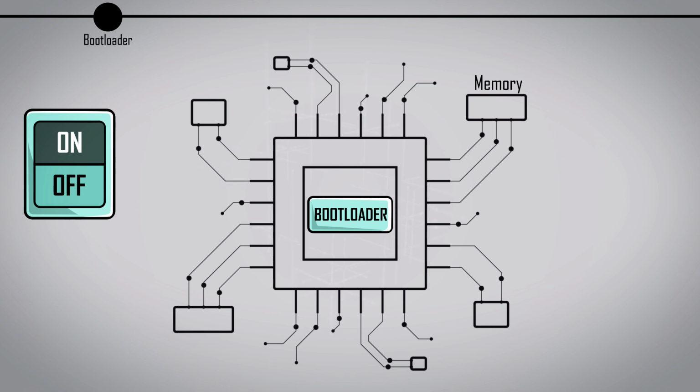The bootloader is often referred to as a bare metal program, meaning that there are no other programs running underneath it to help support its operation on the platform. It is, in a sense, the program that's closest to the bare metal of the chip that interacts directly with the hardware. In contrast, applications a programmer would write on an OS are not bare metal because they don't need to have the know-how to interface with the hardware directly.